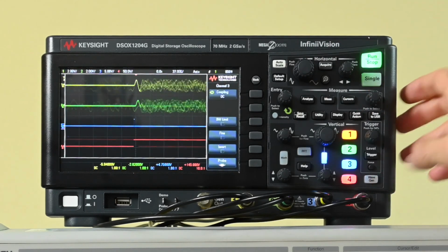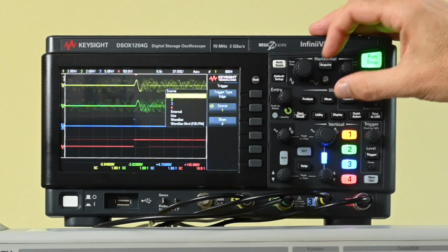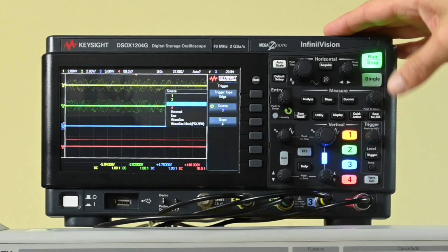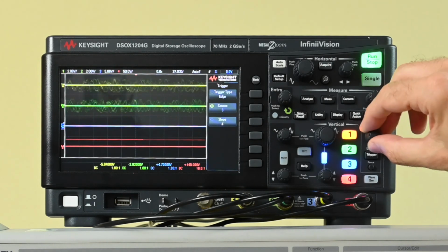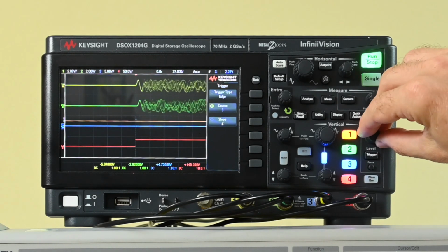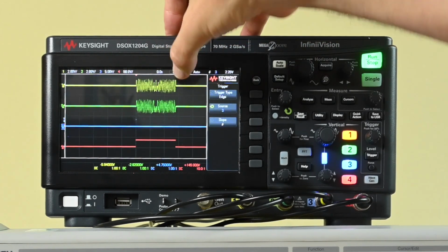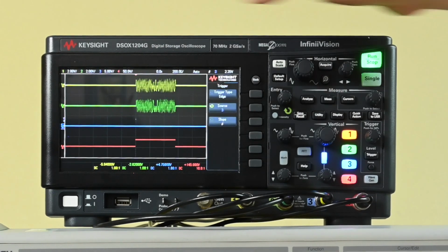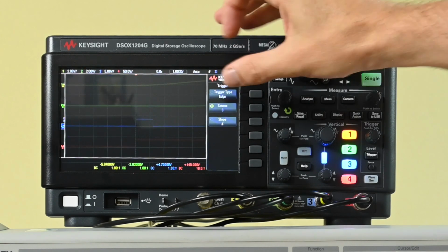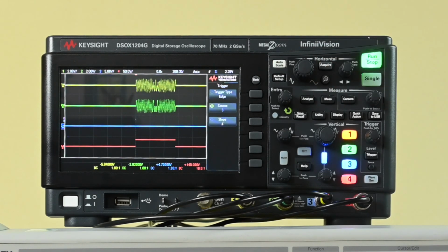So what I'm going to do is I'm simply going to set my trigger on the external source. There we go. Selecting it and choosing my trigger signal. And now I've got a perfect trigger that is coming basically from the blue line here. And I'm now basically independent of the signal itself. So even if this signal would be hard to trigger by itself, I can just use this burst signal here, and in this particular case I could also be doing it on the red one because it happens to be the same. But yeah, this is going to be very flexible in terms of being able to investigate the device or sync it to other devices that you later need to connect to.